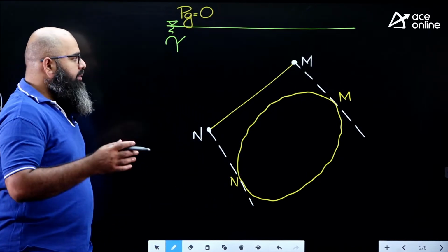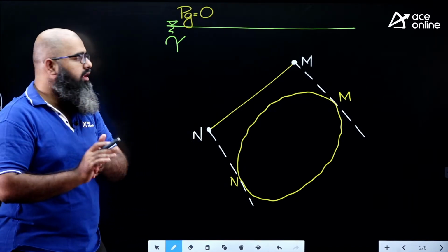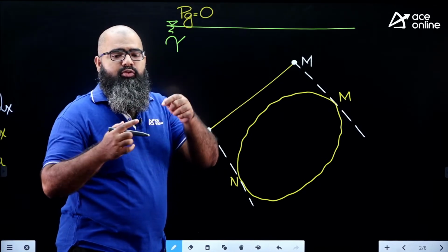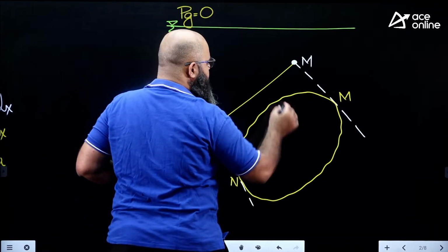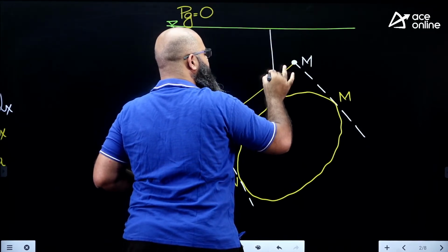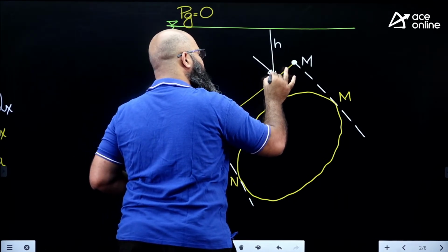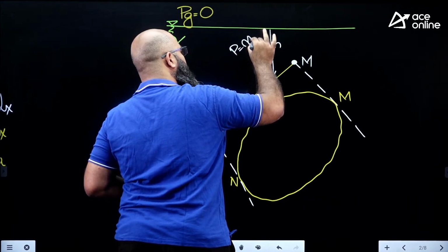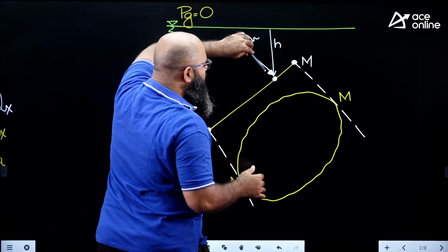Now come to think of it, the moment this plate is submerged, imagine the thickness is 0, mind you. On every differential area there is going to be some pressure intensity acting. For example, take a position over here, at a depth of h. There has to be a pressure intensity acting here. How much is the pressure intensity? Pressure has to be equal to gamma times h. Is it not?